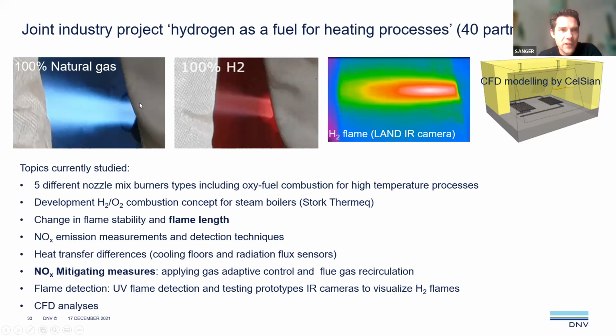And as a result, what you can see here, we have a ceramic tube, that's the black tube. But if we switch to hydrogen combustion, then you see that the black tube becomes really hot. It becomes orange color. So it becomes around 1000 degrees Celsius or 800 degrees Celsius. So you get a lot more heat is produced already inside of the ceramic tube when you switch to hydrogen combustion. And I'm not saying that the ceramic tube will be damaged, but maybe on the long term